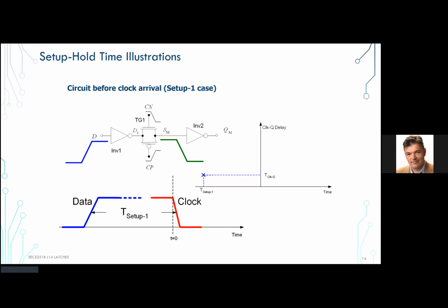All right. So when data arrives into a transparent latch, it does not affect any of the waveforms we have over here. Essentially, my D to Q arrives into a closed latch. If it arrives anywhere in there, it does not affect the propagation delay.